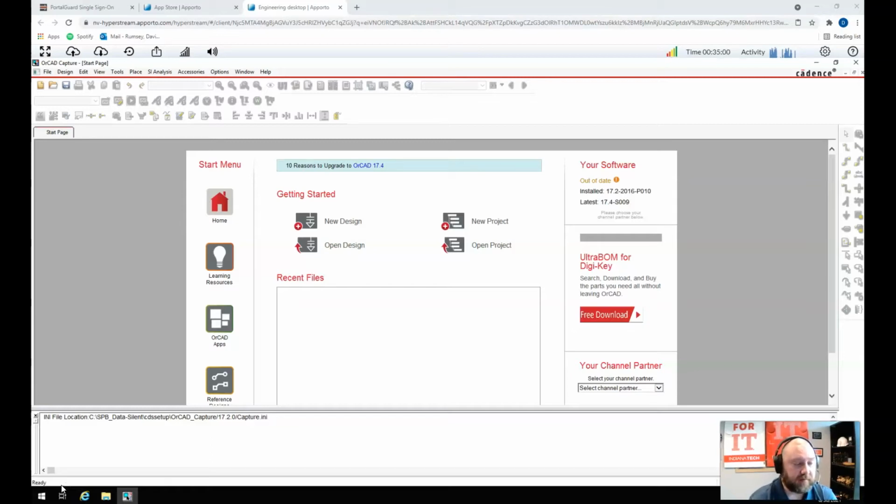And I've already launched the program because, as is seen in the last video, I don't want to wait a lot of time for it to launch. So I'm going to go over here, and whenever we're doing an assignment or a simulation, you always want to choose the new project as opposed to the new design option. There are reasons for that. The main reason is the new project means that you're actually trying to do simulation. A new design doesn't necessarily tie into simulation, even though you might think it would.